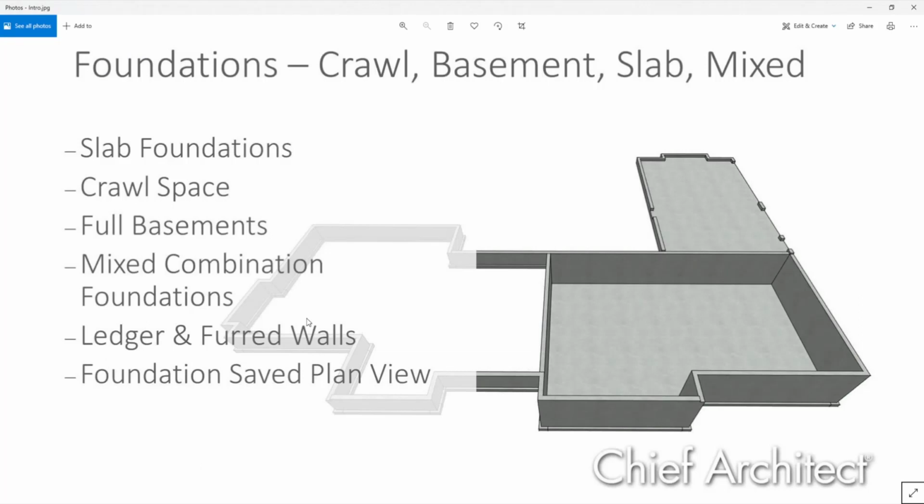Hi, this is Marge from Reed Springs, Missouri. I'm still working on this style house. This intersection is 20 feet wide, and they're going to be load-bearing walls. When I do the auto foundation, it puts a full stem wall. I have a 48-inch stem wall on top of the footing. And I'm thinking about what you did on those walls earlier. Could I take those and change those from the full stem wall to a pier and post?